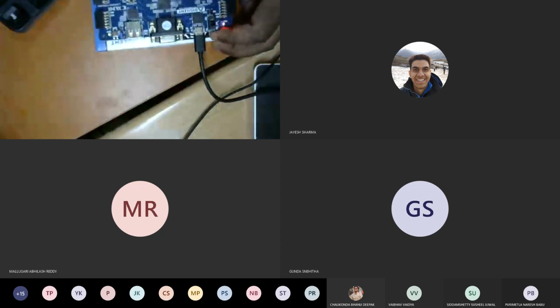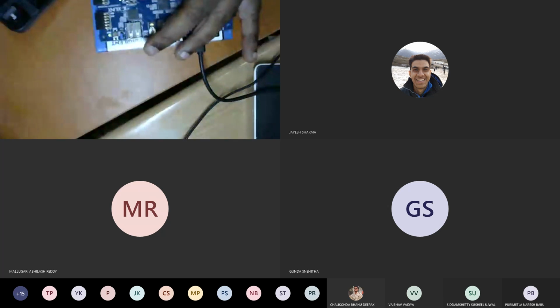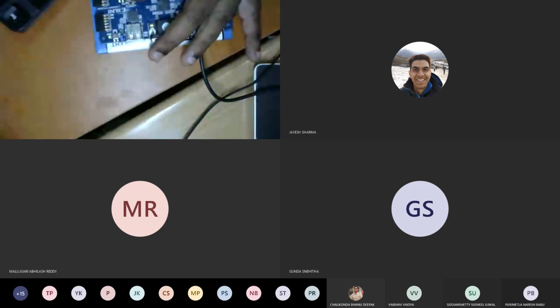Now if you see, the reset equal to 0. Since my J and K equal to 0, what should happen? Of course, the reset is active, so nothing will happen. Now we release the reset. If J and K equal to 0, whenever the clock pulse comes, it should maintain the same state. Now if J equal to 1, J is kind of a set input. If the clock comes, it should be set to 1.